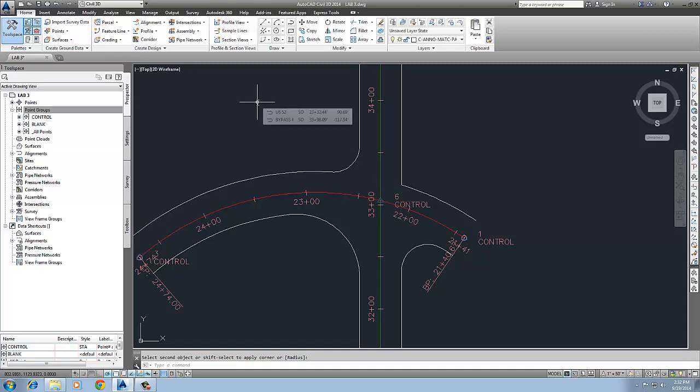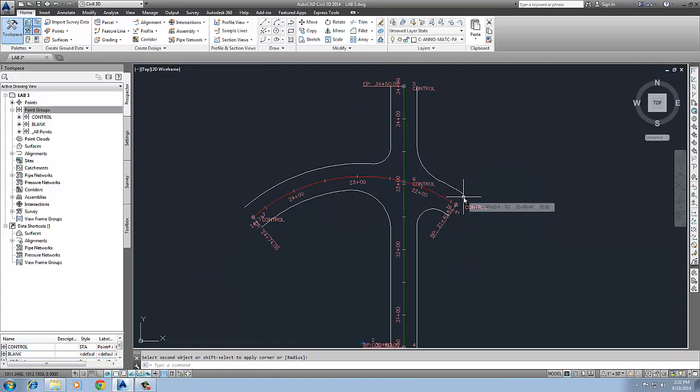And we're going to go another fillet, and I'm going to go to the radius this time and reset it. If I was thinking I could have done the 60s all at one time and the 25s, and you just gotta kind of think about what you're doing sometimes. So it's as hard as that. When we get into this, we can see that what we have now are compound reverse curves developed. And again, Fillet can be a really wonderful tool for doing that.